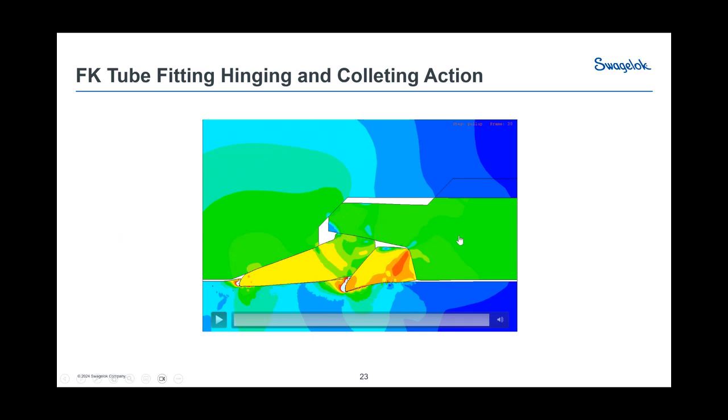How the fronts and backs work. You'll notice on the outside of it, there's this long nose. We affectionately call it the diving board, and it comes down and hits the body. And there's a 45-degree angle there. That gives you your torque spike when you go ahead and make up the part. Because of the angle, it allows you to advance it slightly every time you remake. That allows 25 remakes of any assembly in any body.